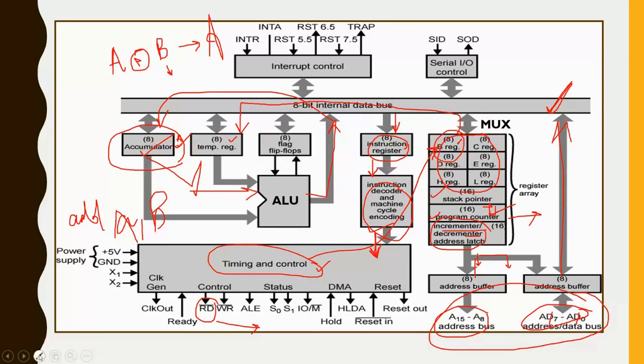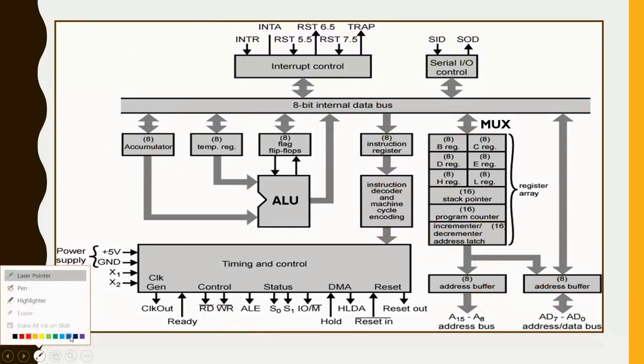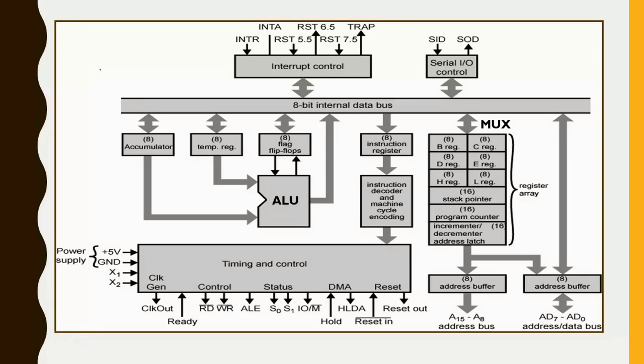And yeah, the main important thing which I forgot to tell you, right? We are working over 8 bits, because we have 8-bit registers. But if we need to add 16-bit numbers, what we can do is pair the registers. So in 8085 we can pair BC only, we can pair DE only, and we can pair HL only, right? We can't pair B and E or D and L. So this is specific, right?